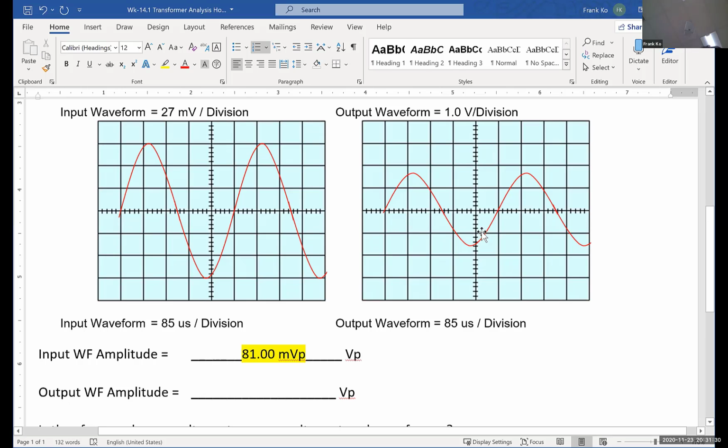But take a look at the negative peak. The negative peak is almost right on top of the center vertical line where the graduations are. And if you use the negative peak, because it's closest, almost on top of the center vertical axis, and look at the graduations, can you verify, do you concur with your classmate that this looks like 1.6 divisions? Yeah. Everybody okay with that?